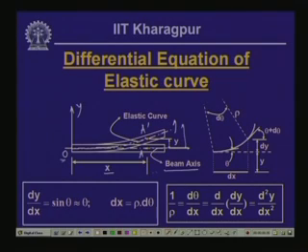That means, as we saw while deriving the bending formula, that the strain at the neutral axis level is 0. So, we assume that there is no stretching of the axis of the beam. Now, let us consider a small segment after A, a distance AB having a length dx,